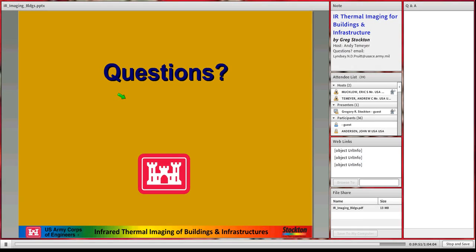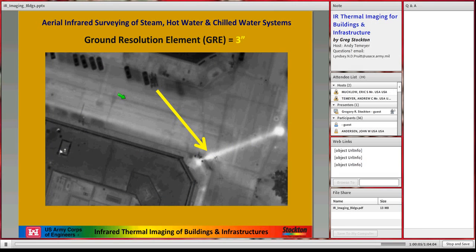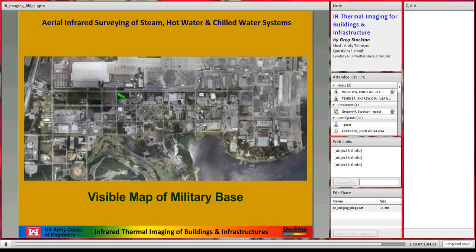Now, the question from Hawaii, what was that again? Yes, basically, when you're doing thermal imaging in Hawaii, what time of day would be the best time to do thermal imaging on a building? Early in the morning before sunrise, or a few hours after sunset, or something else? You just want to have a delta T as large as possible. And by the way, I volunteered to go to Hawaii. But you want the largest delta T that you can get between the inside and outside.